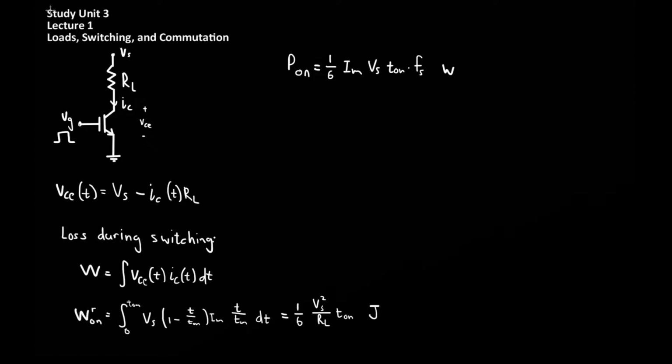type of load. Examples are, firstly, the type of load, which is usually inductive and rarely purely resistive. There's also a switching mechanism classification, which determines how the load affects switching commutation, things such as hard switching, resonance, soft switching. And finally, the switching characteristic required to fulfill a specific VI requirement, such as a bidirectional current switch or an asymmetrical sustaining voltage switch, and so on. These factors all need to be taken into consideration when deciding how the load will be switched and what type of switching will be used.